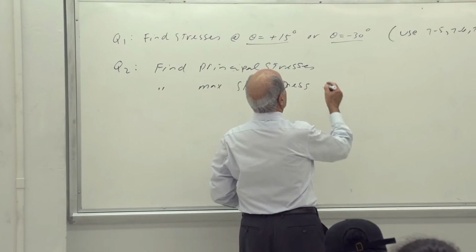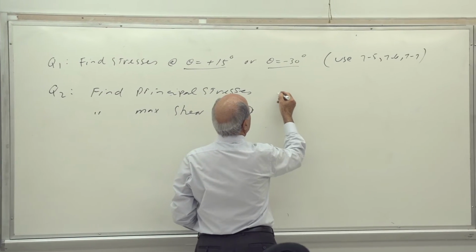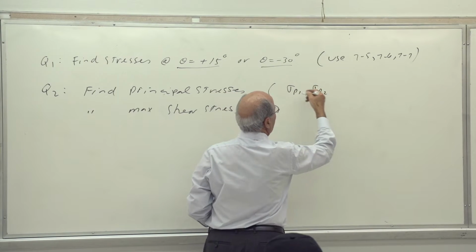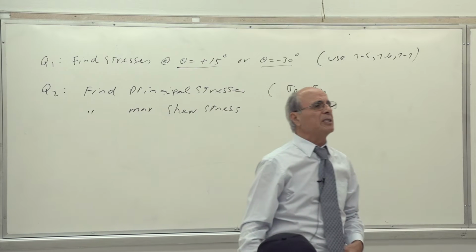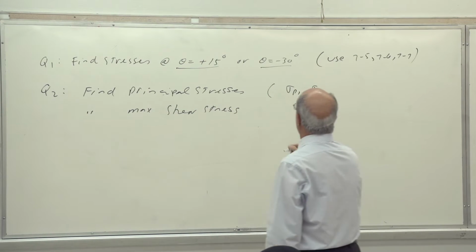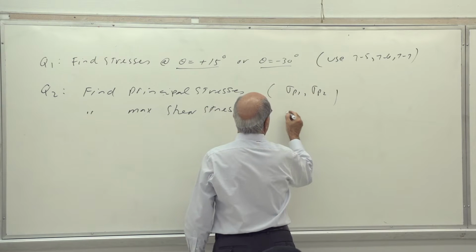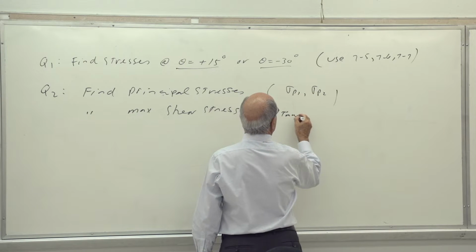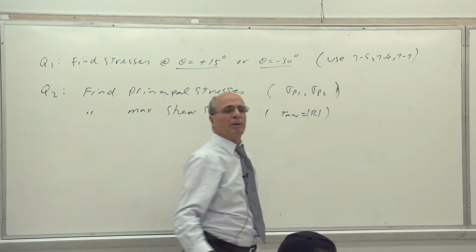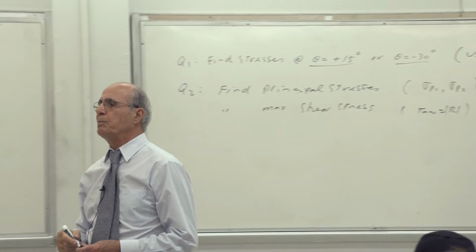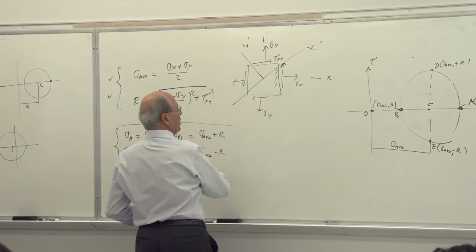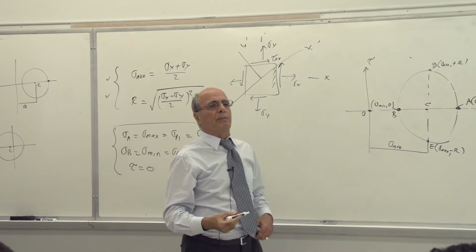For this one, draw the Mohr circle, and then from the Mohr circle, you just get sigma principal 1 and sigma principal 2, or you can call it sigma A or sigma B. Is that understood? Yes? Which I'll show you there, correct? This one is also very important: tau max is equal to R. I just put the magnitude, because the sign I will explain after we plot that, correct? All you need then is this calculation, which is a very simple operation, yes?